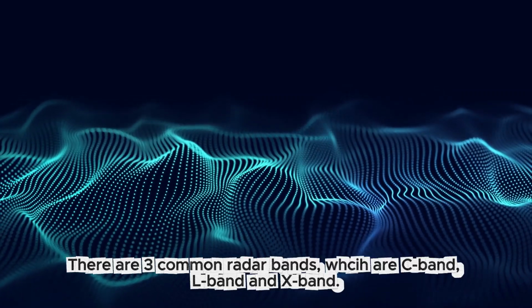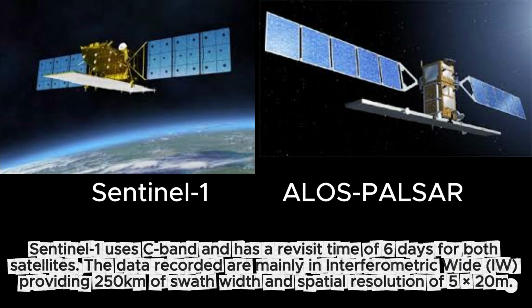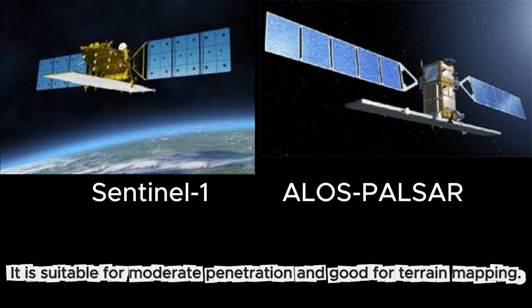There are three common radar bands: C-band, L-band, and X-band. Sentinel-1 uses C-band and has a revisit time of 6 days for both satellites. The data recorded are mainly in Interferometric Wide, IW, mode, providing 250 kilometers of swath width and a spatial resolution of 5 by 20 meters. It is suitable for moderate penetration and good for terrain mapping.